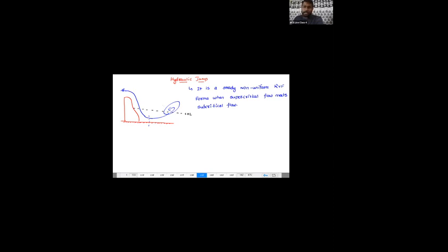So now you tell me when the hydraulic jump is going to be created. So this is nothing but reverse of flow or not. Now this water level is going to rise, and again it is going to be uniform. Okay. So now you tell me, while it is rising, this is nothing but a third profile, yes or no? And then there is a hydraulic jump when the flow from the supercritical meets the subcritical.